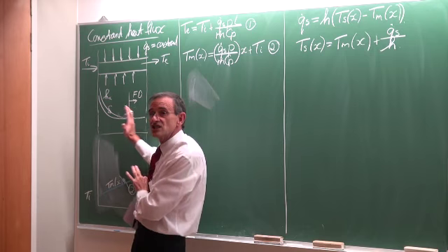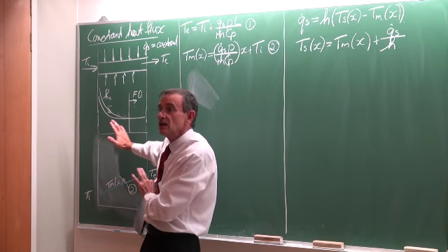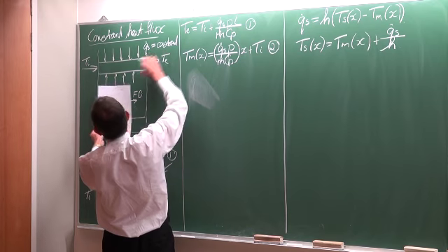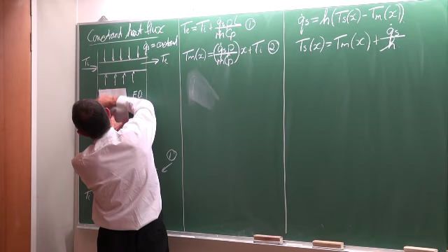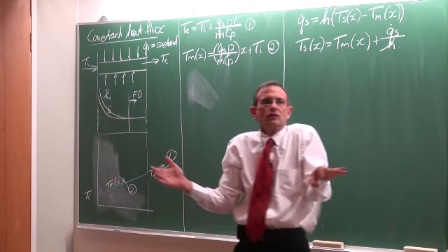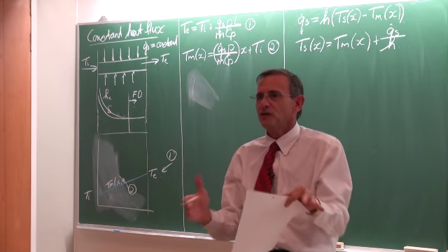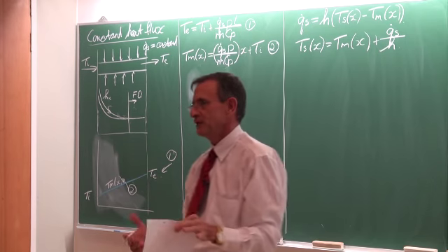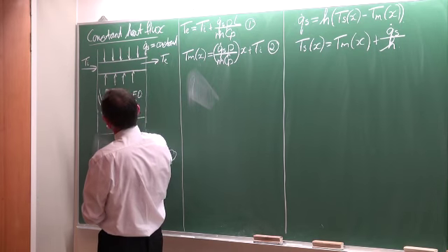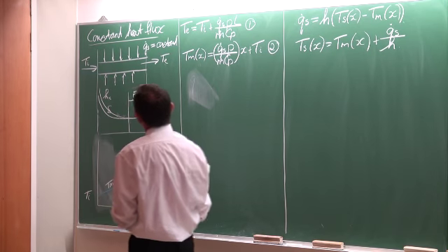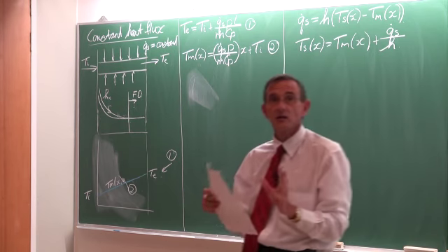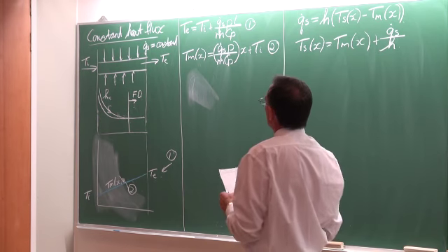Now this sketch is just a schematic, of course. If the flow is turbulent, as we've said, and this is a very, very long tube, then all this will happen in a very small distance, and in general, it would be a good assumption to say the flow is always fully developed. Okay, but it depends then on whether the flow is laminar or not, and how long the tube length is in comparison with the diameter.